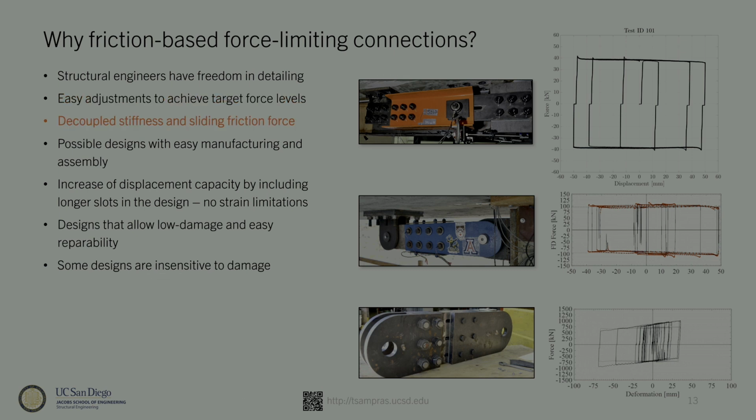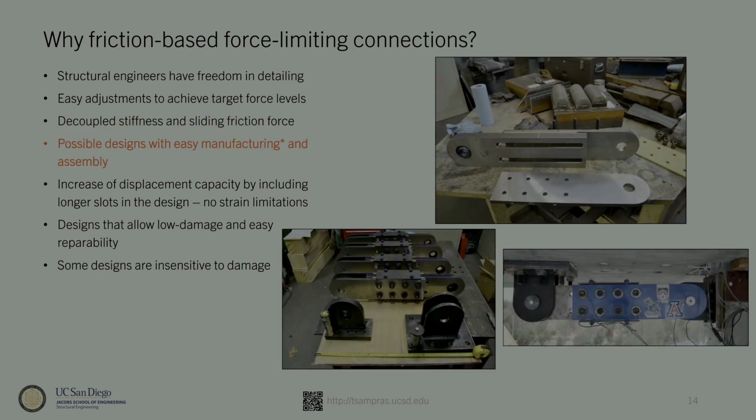And the nice thing is that you decouple the stiffness from the strength, essentially. You can have a very high stiffness that is not affected by the sliding force, which is one of the topics that you have to consider in yielding mechanics. Like the stiffness and the yielding force are coupled.